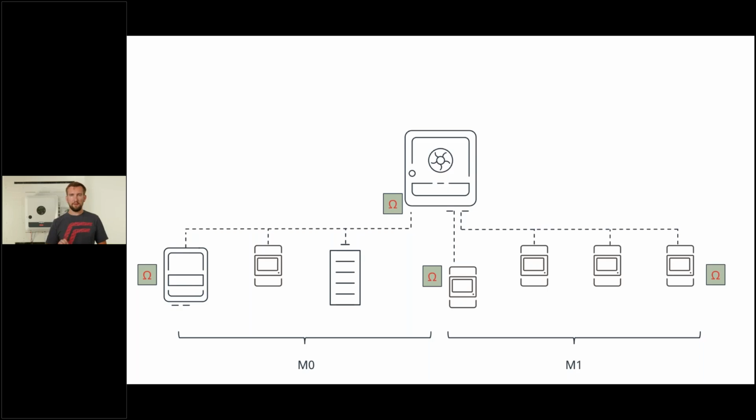In this case, take a guess what we do with the M1 resistance in the inverter. It is switched off, obviously. We switch that dip switch to 0 to deactivate it so that the signal can pass along the entire length of the line.